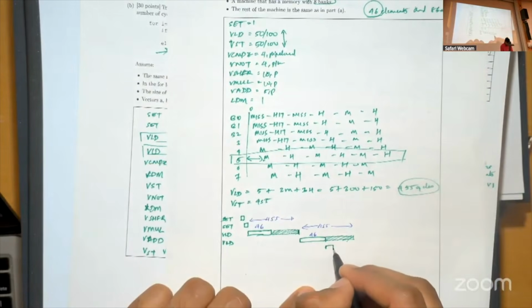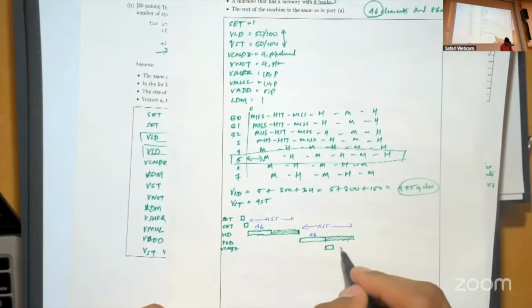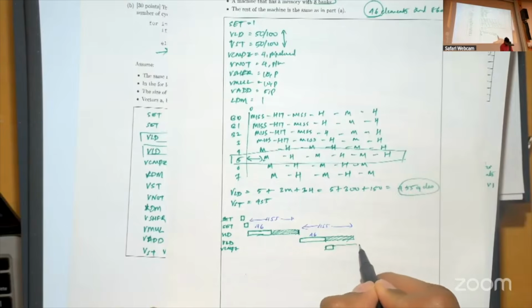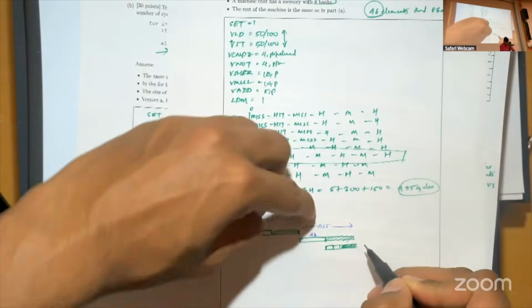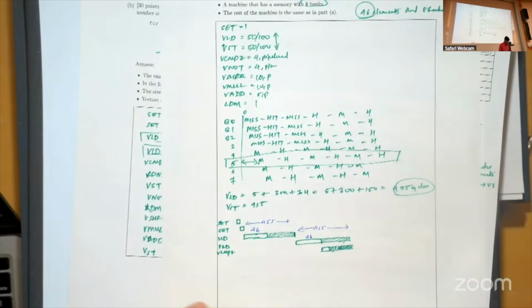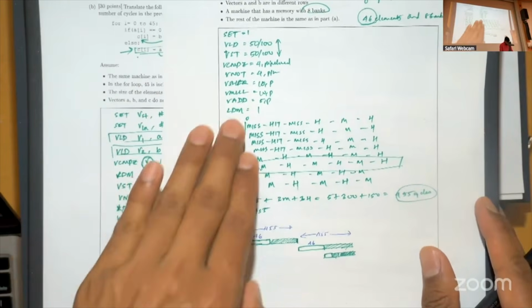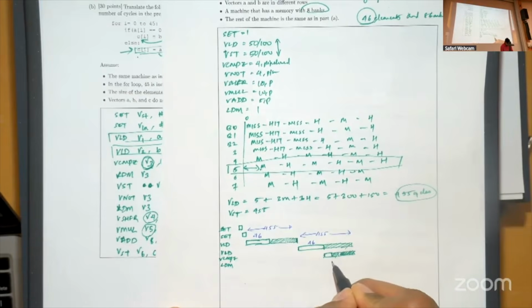And the vCompare instruction takes 4 cycles to start off, and then it's pipelined. So this is the 4 cycles it takes to start. This is vCompare 0, and then it's pipelined for 45 cycles. And it will be hidden behind this because this is 455. It's going to be much longer. Anyway, after vCompare 0, you have the load M, and load M takes 1 cycle. So load M is also nicely hidden behind the memory access latency.